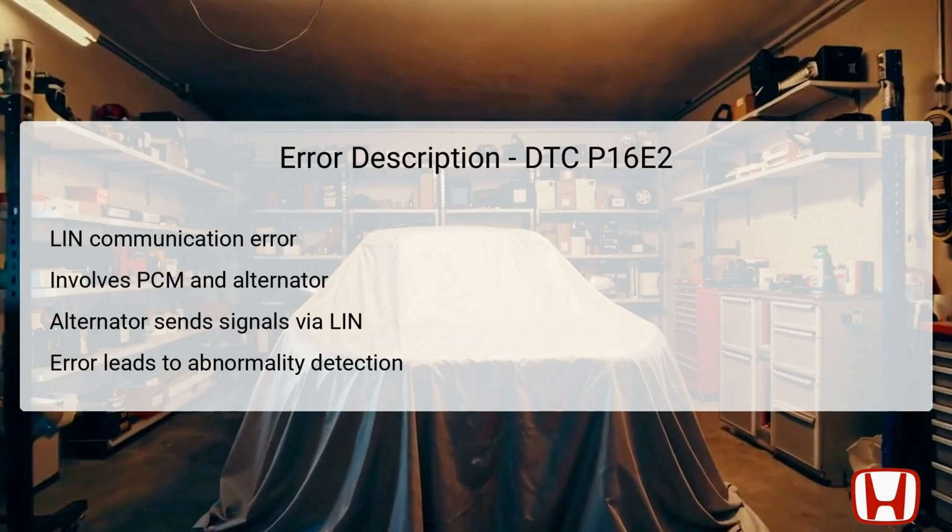The alternator itself is located in the engine compartment, typically near the top front of the engine. It is vital to inspect this area thoroughly for any loose connections, especially at the +B terminal, which is known to contribute to this error when not secured properly.